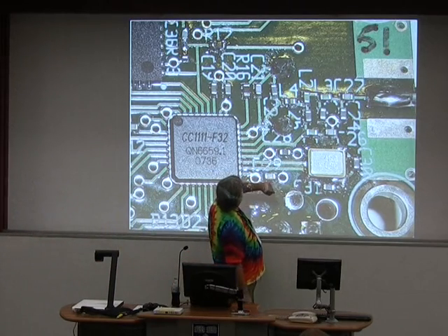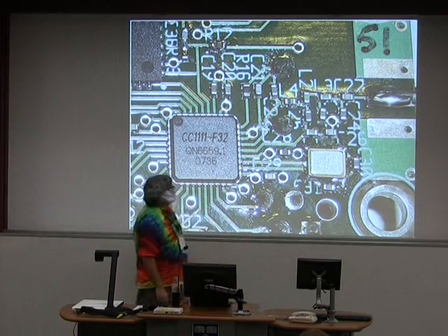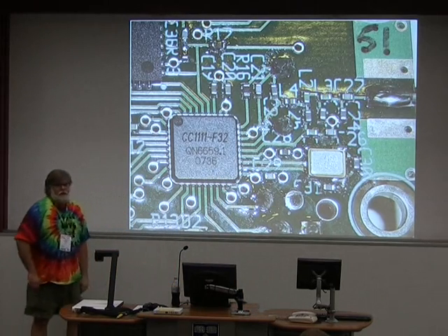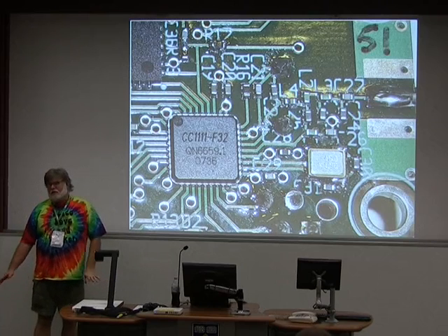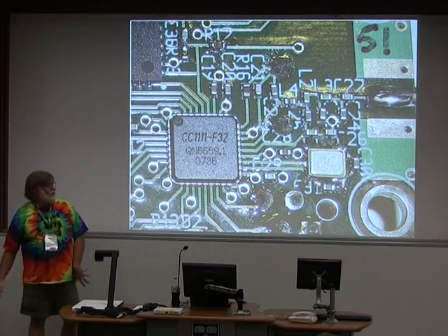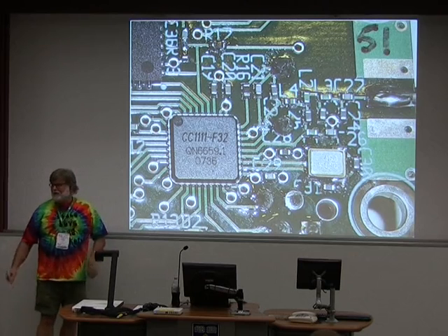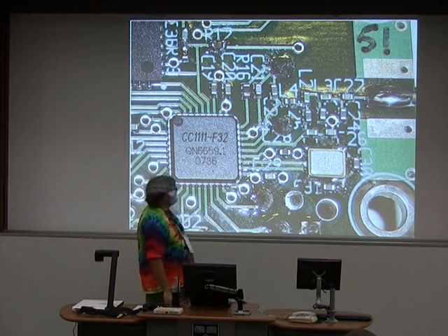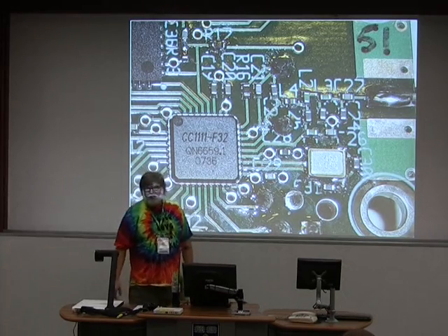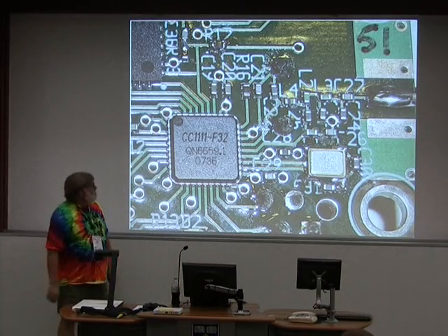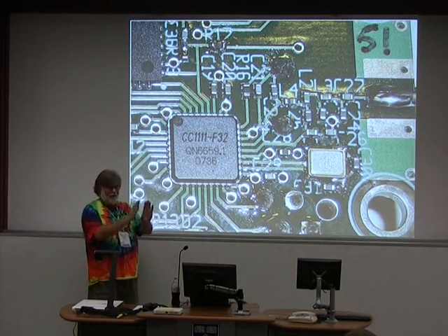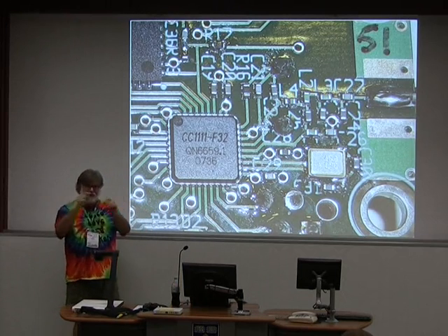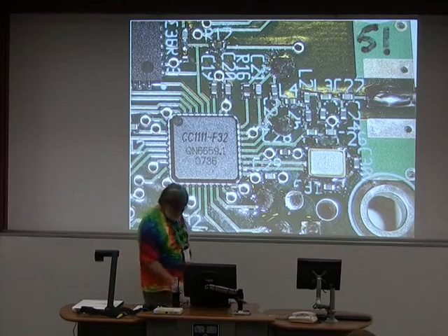Likewise, on this board there aren't many situations like that, but you have to not throw away everything you know about radio design just because you're doing surface mount cute little parts that are all gorgeous little rectangular solids. Those really are inductors, and they behave like inductors, and they have EM fields around them, and if you line a whole bunch of them up neatly on the board, they will all couple to each other and just work like crap.